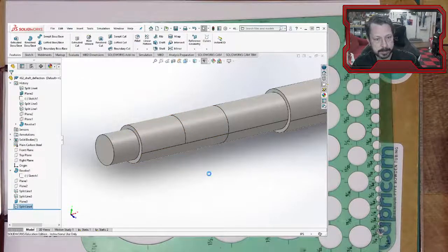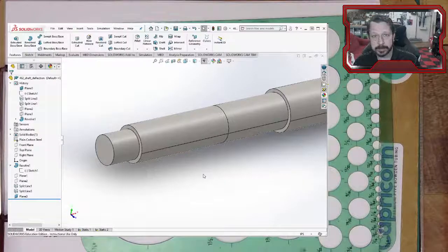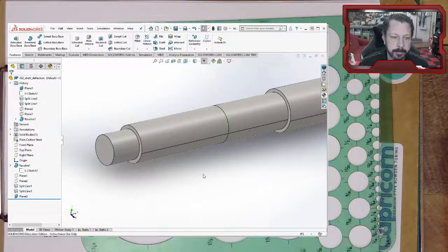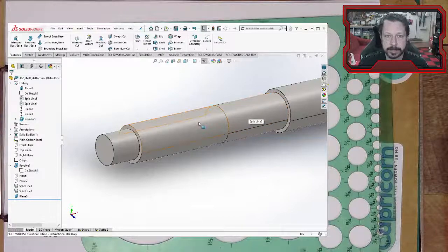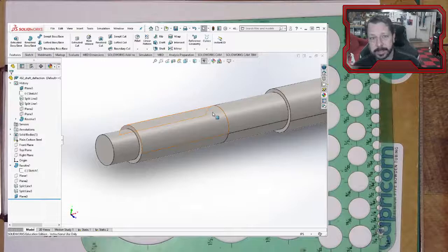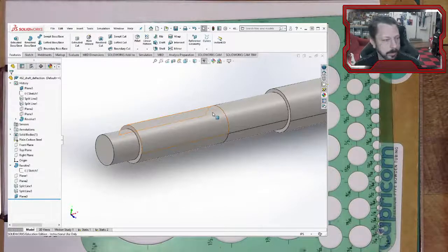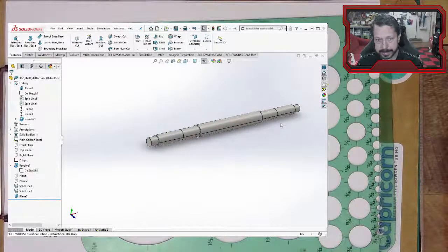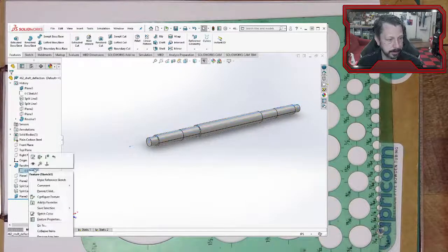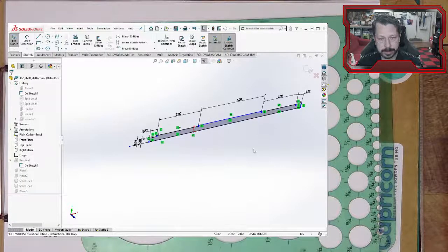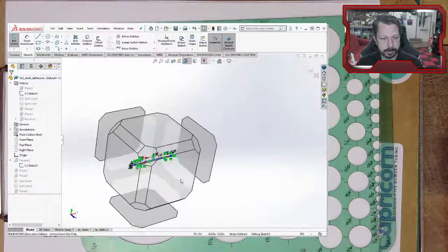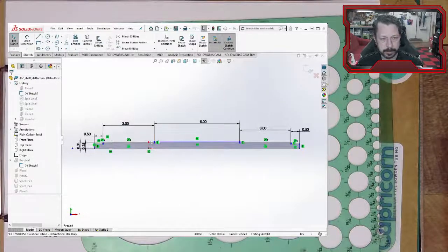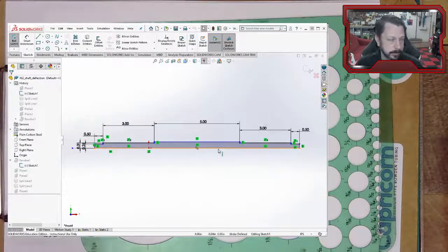Now, I don't actually want that. They don't have any effect on the deflection or stress or anything. But it splits up surfaces so that you can do things in just certain locations. Sometimes you need that in the simulation to apply a load at a certain point or something like that. And that's what I'm using them for. All right, so I showed you this already, but other than that, all we did was, let's look at it from this side, build the profile and revolve it around this axis down here. So it just did a revolution. That's all it was.